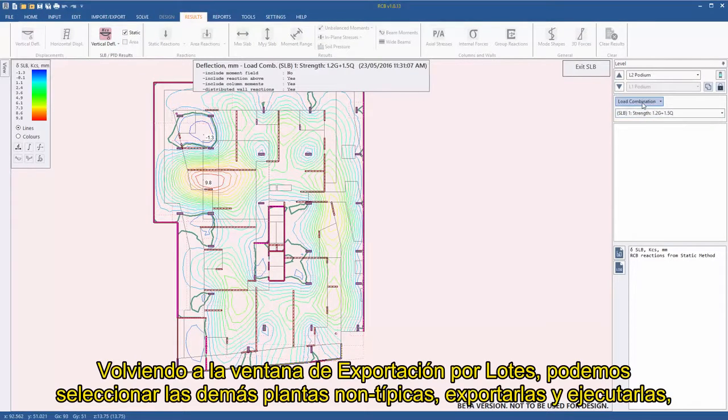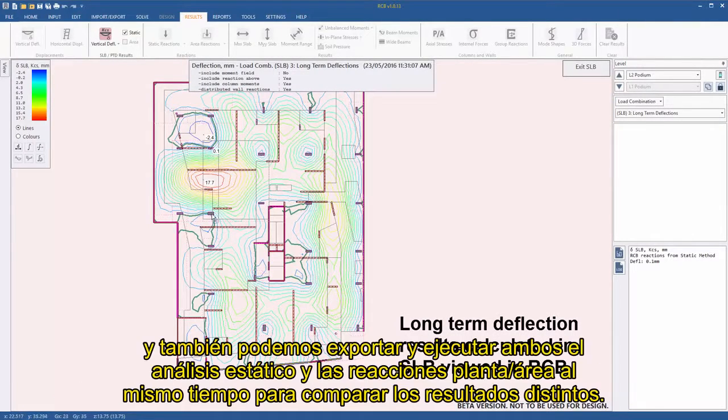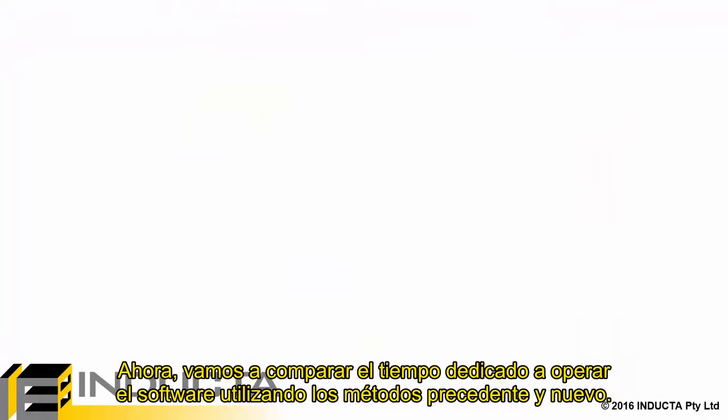Going back to the batch export form, we can then select all other non-typical floors and batch export and run. And we can also export and run both static analysis and floor area reactions at the same time to compare the various results. Now, we will compare the time spent operating the software using both the old and new method.